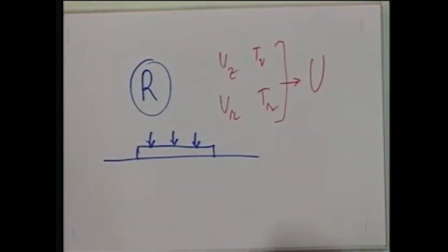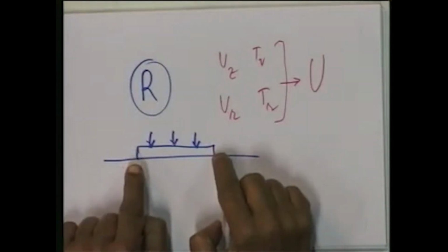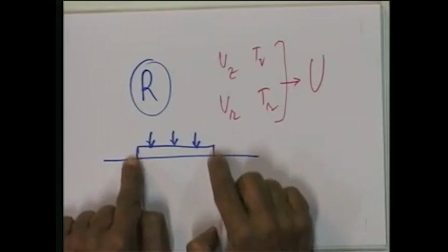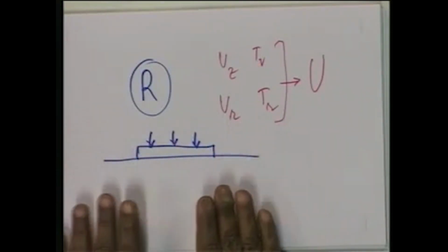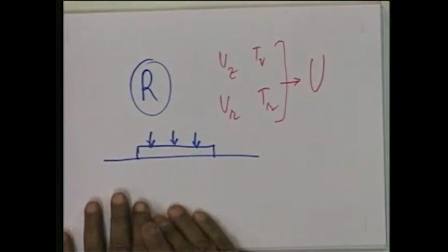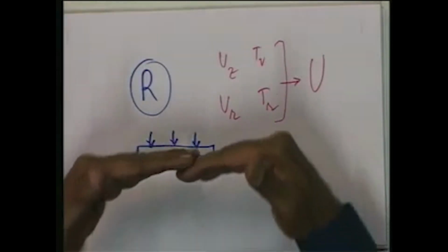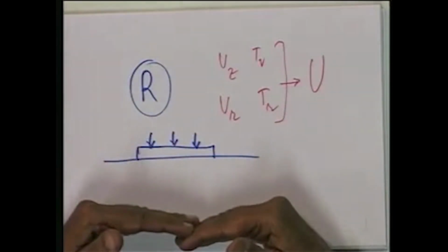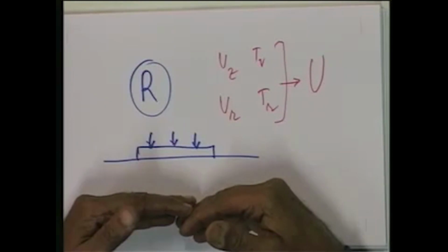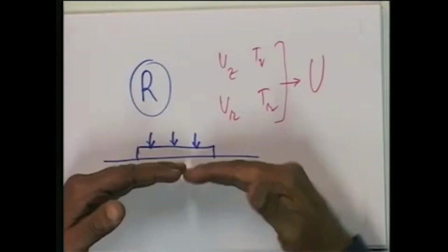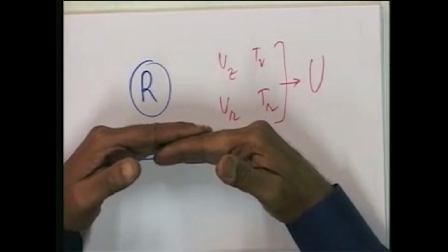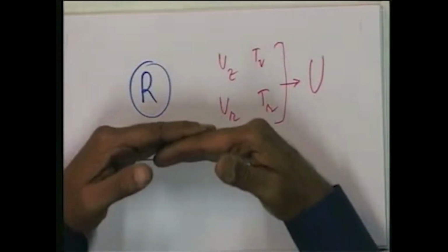Then, depending upon the relative flexibility of this loaded area compared to the soil, whether this loaded area is flexible or rigid, will determine how the consolidation phenomenon is going to take place, whether it is going to take place under the so called free strain condition or under the fixed or rather equal strain condition.